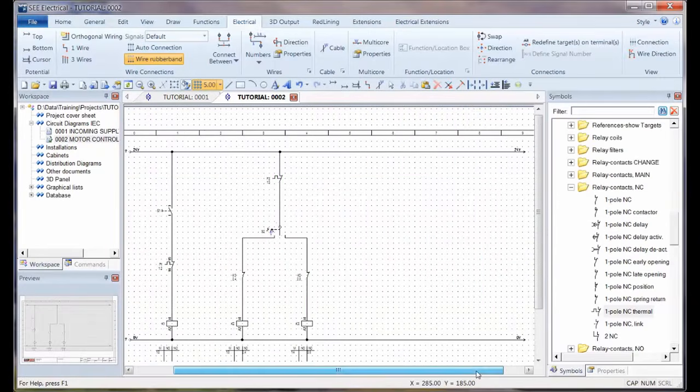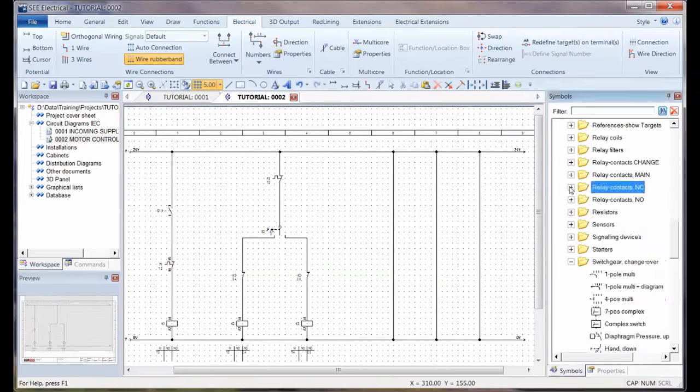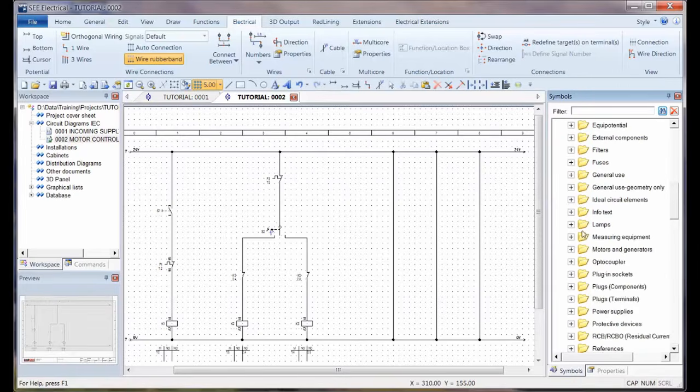We're going to put some wires across on the right hand side for indication. We're going to put some lamps on there. So I'm going to draw one down. I'm going to hold down the number 2 and drag and let go at this point. That's an array copy. I want 2 copies of that. So you hold down the number of copies on the keyboard and drag an object. So I'm using shortcuts. It's always good to know the shortcuts.